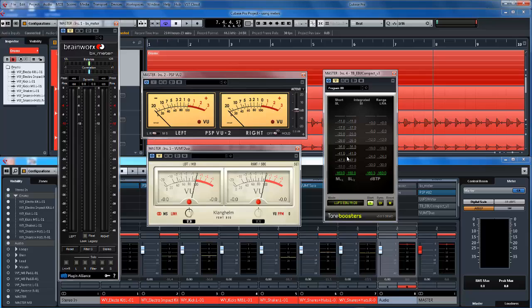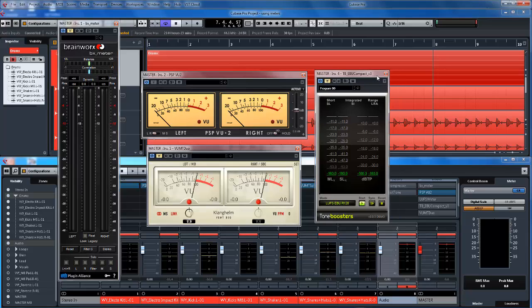We spoke about that. If we want to get more accurate, we need to extend the oversampling ratio. So if you want to have the most accurate, and I think in the Canadian standard, they're down to 0.2. I'm not sure if that's 8 or 16 oversampling. But the problem you've got with higher oversampling ratios is that they really murder the CPU. So 4 is fine for what I need.